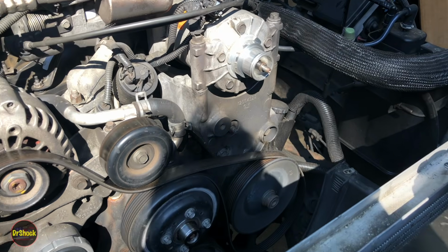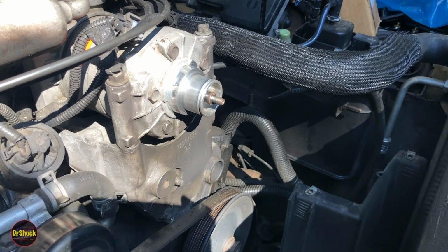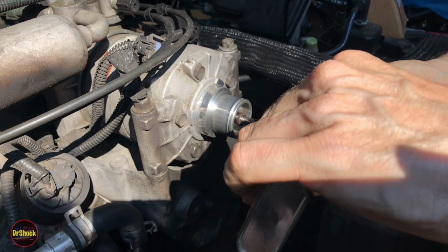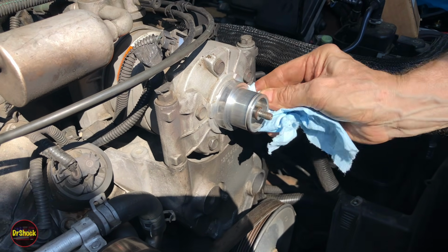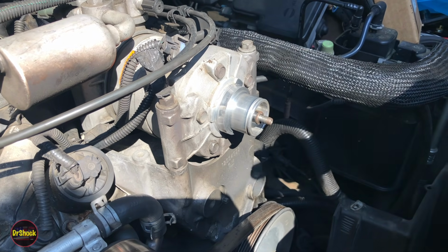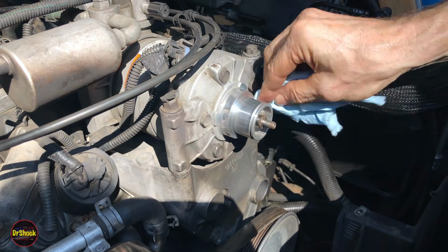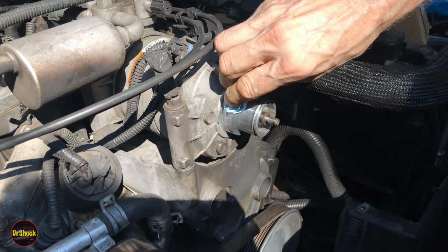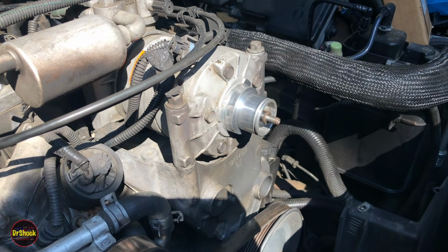So to replace this, what I'm going to do, let me get a small paper towel here. When press fitting on something like this, I like to take a little bit of 3-in-1 oil. So we'll put some of that all around here, and again, this helps make sure that we've got all the grit off. And while we're here, we'll go ahead and do the bearing surface for the pulley. Even with that, you get a little bit more dirt that comes off with the oil. I'd rather use the oil than brake clean or something because it'll help a little bit with the reassembly.